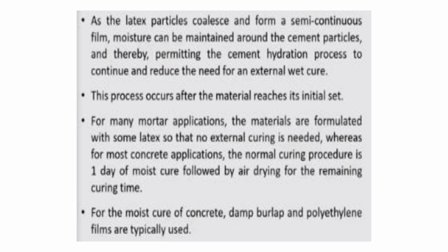As the latex particles coalesce and form a semi-continuous film, moisture can be maintained around the cement particles, thereby permitting the cement hydration process to continue and reducing the need for an external wet cure. This process occurs after the material reaches its initial set. For many mortar applications, the materials are formulated with some latex so that no external curing is needed, whereas for most concrete applications, the normal curing procedure is 1 day of moist cure followed by air drying for the remaining curing time.